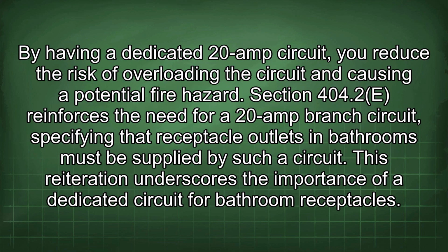By having a dedicated 20-amp circuit, you reduce the risk of overloading the circuit and causing a potential fire hazard. Section 404.2(E) reinforces the need for a 20-amp branch circuit, specifying that receptacle outlets in bathrooms must be supplied by such a circuit. This reiteration underscores the importance of a dedicated circuit for bathroom receptacles.